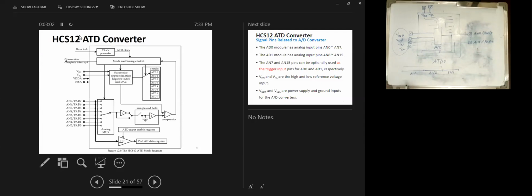It is this, right? So of course, if you increase the number of channels that you are reading from, then your effective sampling period will be n times the sampling period for one channel. So the sampling frequency will be scaled down by n.